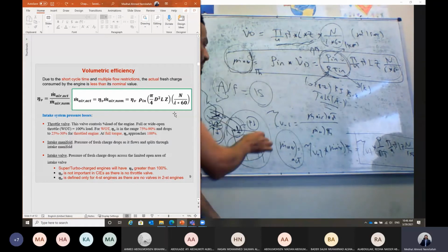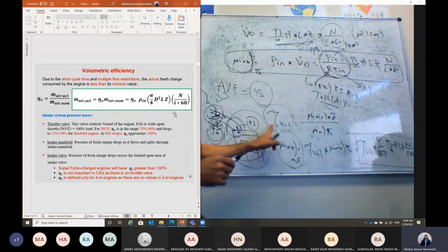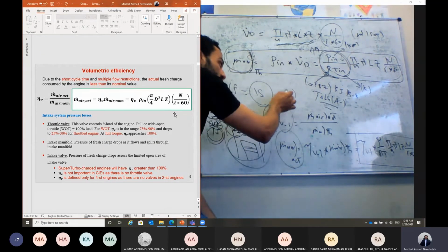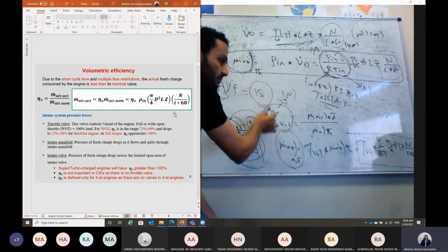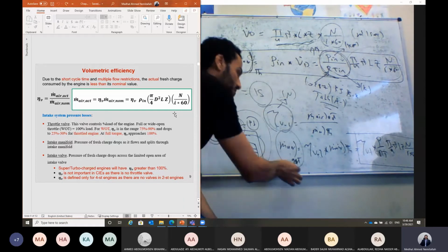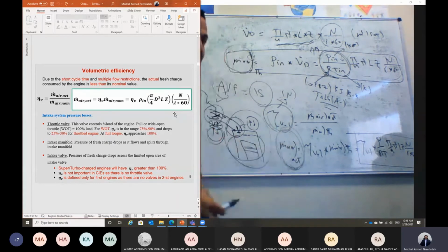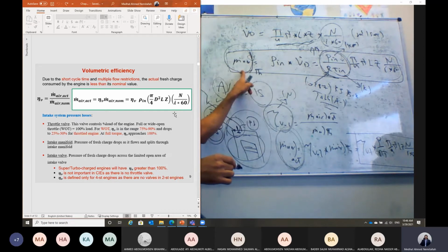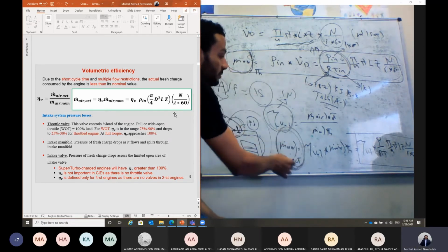So any engine has a definition for the volumetric efficiency as a function of the engine speed, eta volumetric, and those values are already stored within the ECU system. Depending on the engine running RPM, the engine knows the value of the volumetric efficiency, and so has an indication about the actual mass flow rate to the engine. So the ECU does not calculate the theoretical flow rate. It just calculates the actual value of the flow rate.